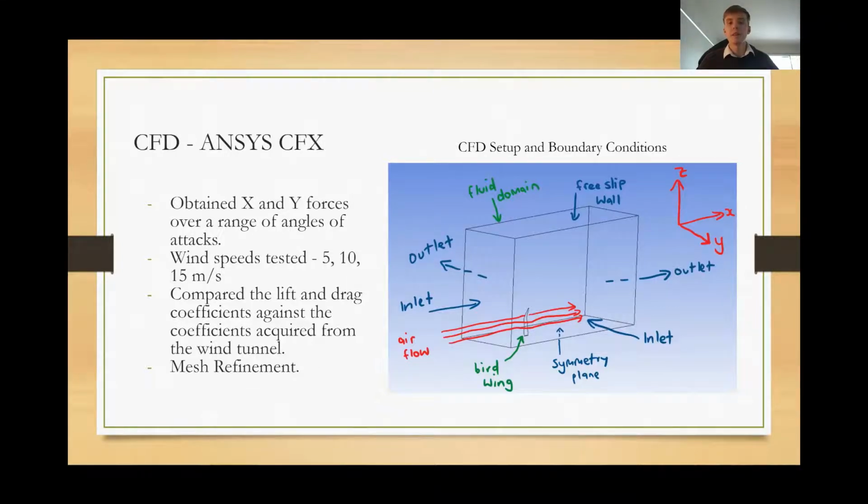We compared these lift and drag coefficient values against the coefficients that were acquired from the wind tunnel. And we did a mesh refinement study just to make sure that the mesh sizing did not significantly affect the values that we got.